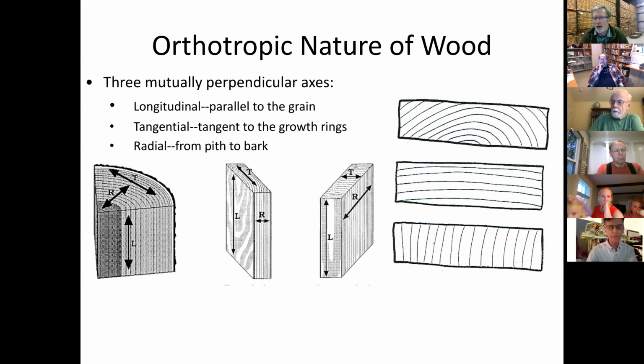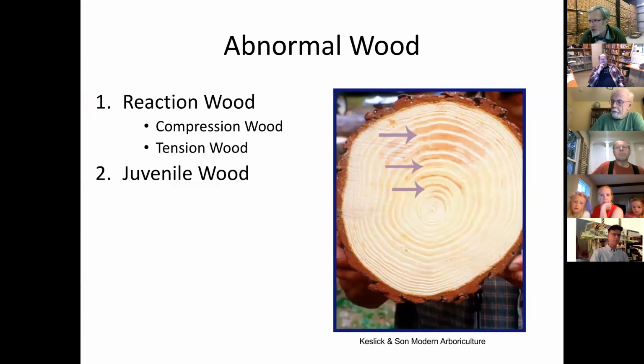This is one of the reasons why quarter sawn wood is so desirable, because if you have a true quarter sawn piece, you're going to have the top and bottom surfaces in width look very much the same and have the same plane of reference. And so they cannot cup. It will not cup unless you see a great difference in the angle of the growth rings between the top and the bottom. That's a lot to take in, right? But just the sheer fact that a piece of wood can have different amounts of the plane of reference in top and bottom can cause wood to warp if the moisture content changes. That's normal wood. Let's talk a little bit about abnormal wood.